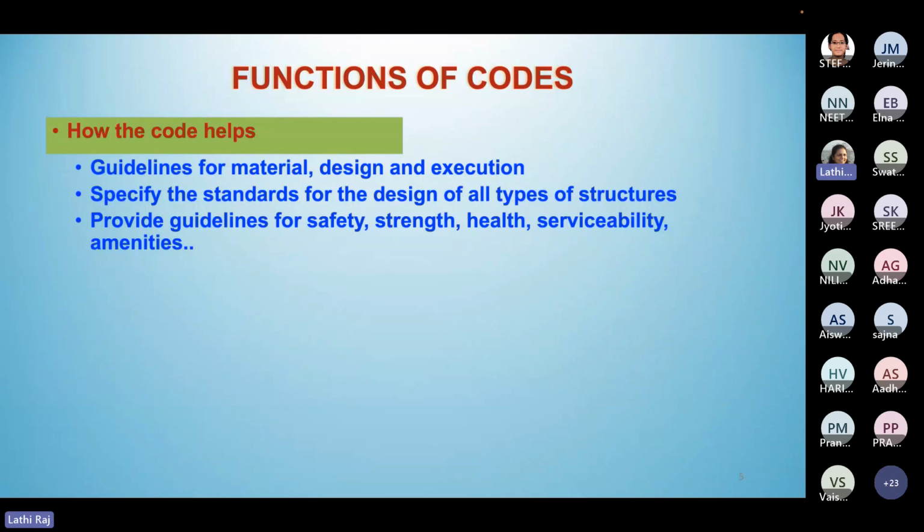One is IS 456 itself. Okay, in IS 456, it gives you the quality of concrete and how to do the mix design. You can refer to another code. Anyone remember that code? IS 10262. SP is the handbook. Okay, and code is different. SP is developed, or SP is given, based on the clauses given in a particular IS code. So any SP you take is an explanatory handbook for a particular code.